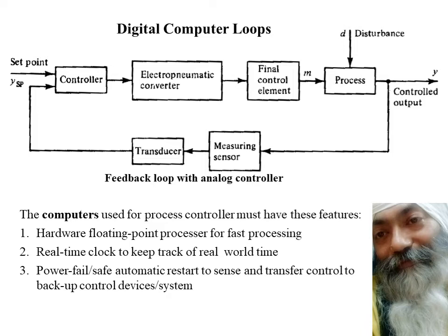Now what happens, many a times there is a bug in writing the software, and because of that the software goes into a kind of endless loop. And you know what endless loops are. Suppose you go in for a kind of loop where it is moving and the breakpoint is never achieved, so it will just keep on rotating in that loop for an infinite number of times. So to avoid that kind of situation where the system gets hung up, to avoid hanging of the computer, we have to have a special kind of timer, and that timer is called watchdog timer.